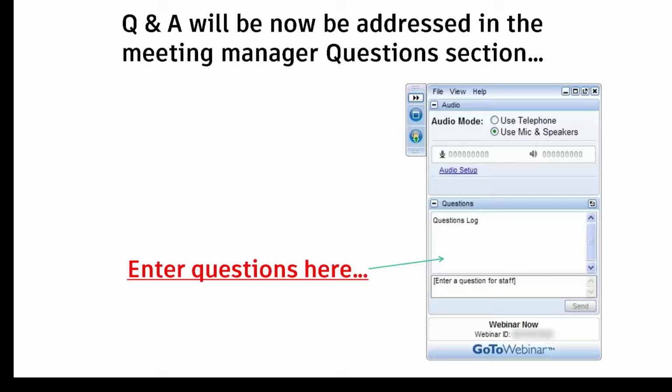And that mesh size can be one of those. The software does a good job at calculating based on that minimum material thickness, but then again, there could be little outliers in there that, for whatever reason, the algorithm didn't find. So the mesh in that area of that small material thickness violates our mesh control settings. So that's where the errors come up.